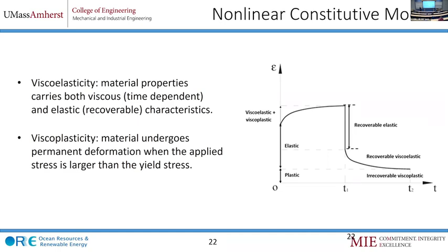What you see in this graph is basically the strain versus time, and how some of the elastic behavior happens almost instantaneously. Viscoelastic behavior takes time. This time delay is what is not captured in existing mooring simulation models. We were curious as to how viscoelastic and viscoplastic behavior affects mooring performance. I'm just going to talk about viscoelasticity in this talk, but Jessica's PhD work actually covers viscoplasticity.